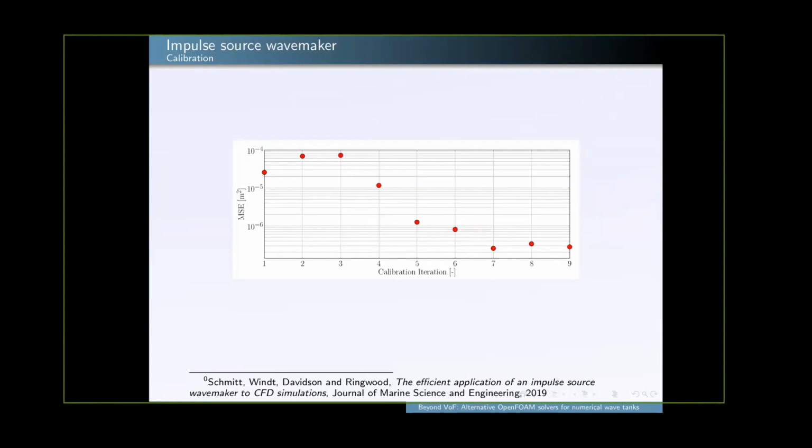So you might say, that's a bit of a headache having to do 7 simulations before you even run your first simulation. Well, if this is a plane wave, which in most cases they are, you just have to do a 2D slice. So you can do your calibration on just one cell thick, and you can run them quite quickly. You do your calibration, you get your input, and then you extend it in the other horizontal direction to get your full 3D tank using the same input. So that takes some headache off.